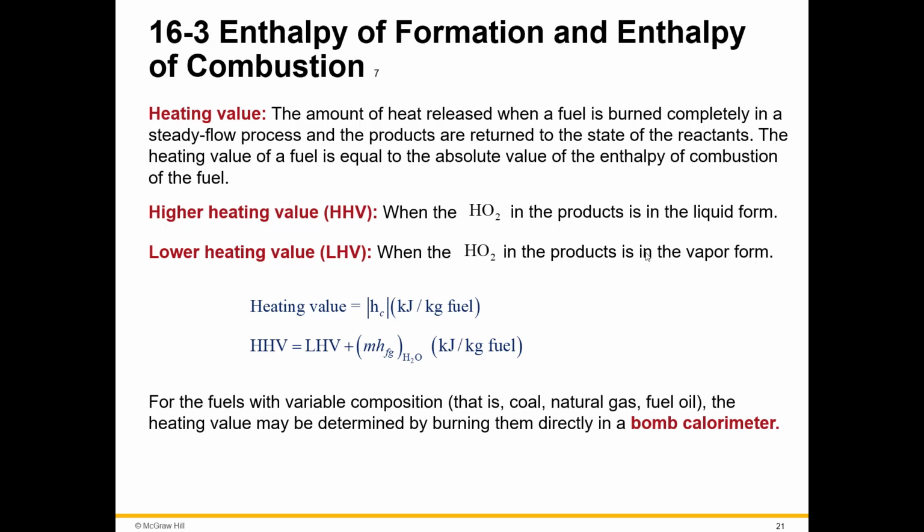So a high heating value, HHV, is when H2O in the products is in liquid form. A low heating value, LHV, is when the H2O in the products is in vapor form. So liquid for high heat, vapor for low heat. Okay? And then you have that there with the units.